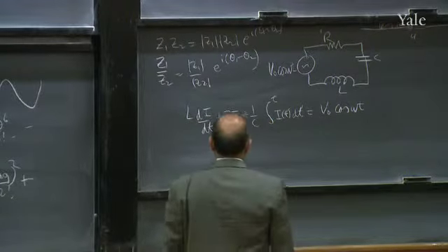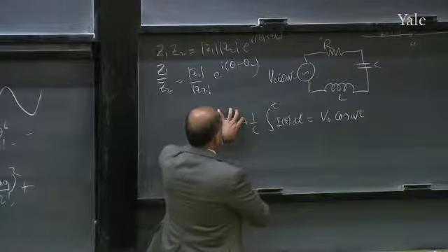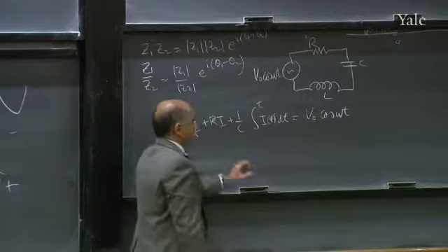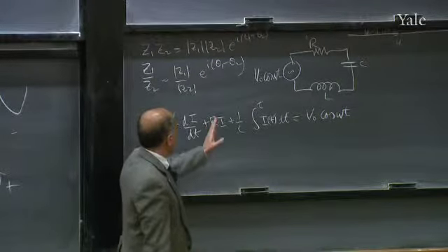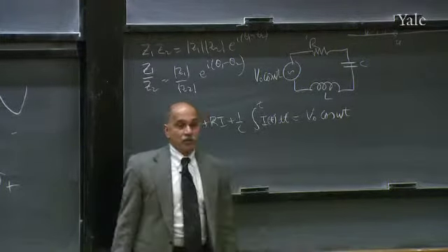In the LC circuit, when you didn't have this term, we were okay, because if you pick a sine, this became a cosine, and that also became a cosine, and you can combine them to get a cosine. But you cannot have di/dt, I, and integral of I all in one equation and all satisfied by a trigonometric function.